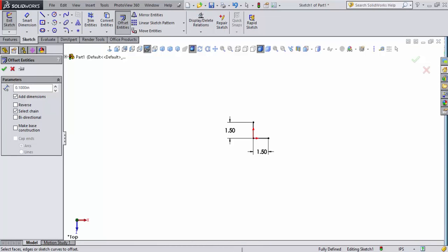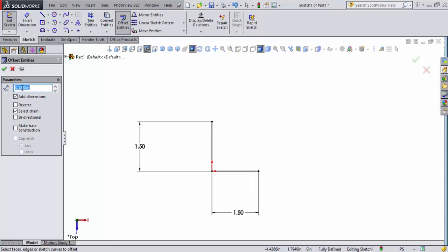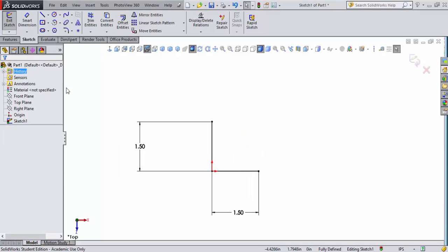Okay, I used my old trusty dial indicator calipers from China, of course, and I measured it, and sure enough, it's 1/8 of an inch thick. So what I'll do is come up here, I'm set to offset entities. I'm going to set my thickness to 0.125, and I'm going to hit tab and let's see where it previews. I can't quite see that. Let me zoom up here and see what I got. I'll select OK, but nope, it didn't work. So I'm going to do that again.